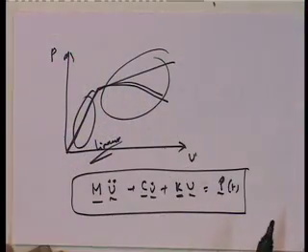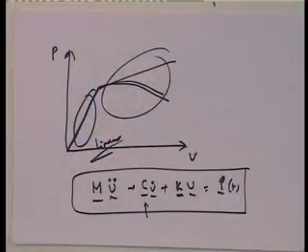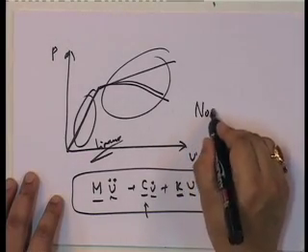So, that is the only time I cannot use mode superposition, purely because you can't use mode superposition. Mode superposition is only valid for linear systems. So, that is when I need to solve this. And the problem is how do I get C when I have nonlinear?